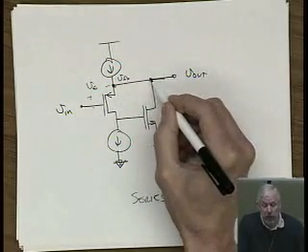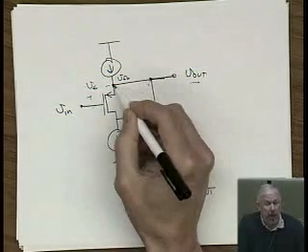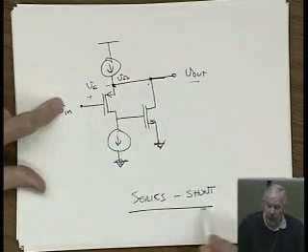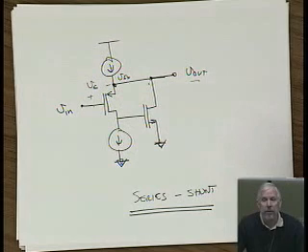And what are we sensing? We're sensing V out directly, feeding it right back to this input. So this is a shunt sensing. So this is exactly right. Series shunt. Okay? Let's figure out the loop gain of this guy. So what's the loop gain?